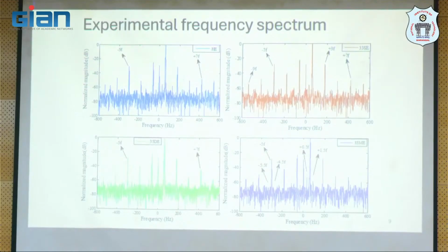So it's very difficult to say what is healthy and what is faulty using traditional current signature analysis if the motor's assembly and manufacturing are not to stringent specifications. This is a lab grade motor, assembled by graduate students working for research purposes. So the assembling techniques might not be very good. Probably when we assembled it as a healthy motor, we introduced a higher degree of eccentricity. There is no way to verify that.